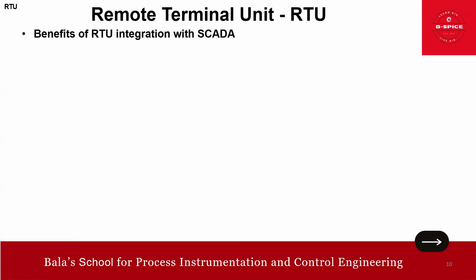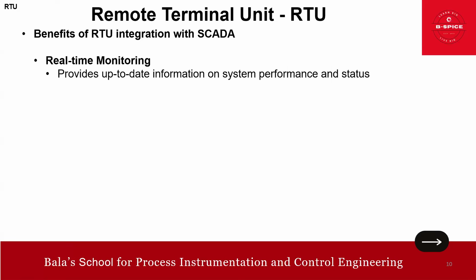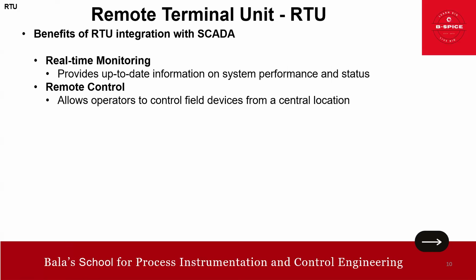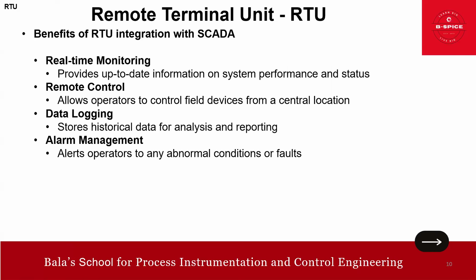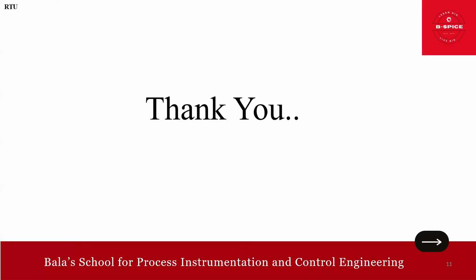Now, what are the benefits of RTU integration with SCADA? Of course, real-time monitoring: it provides up-to-date information on system performance and status. Then remote control: it allows operators to control field devices from a central control station. Then data logging: it stores historical data for analysis and reporting. Then alarm management: it alerts the operator to any abnormal conditions or faults. So that's all I have for RTU working principle and specifications.